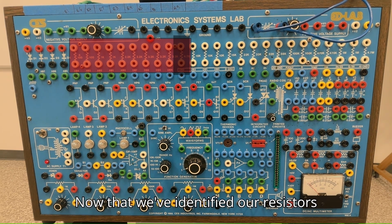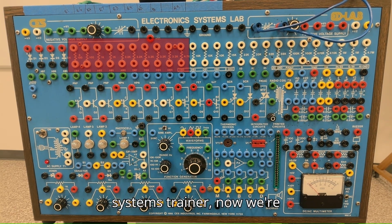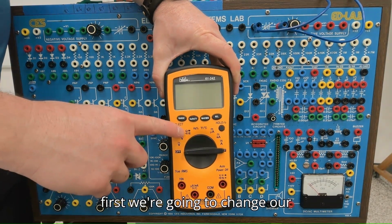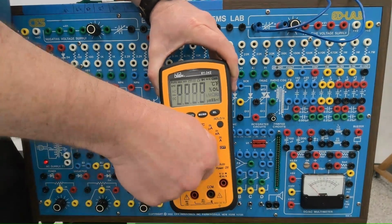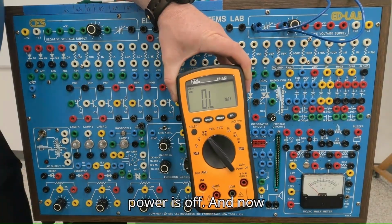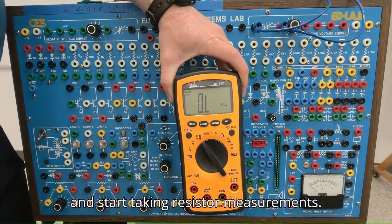Now that we've identified our resistors and their locations on our electrical systems trainer, we're going to verify the resistor measurements again using our multimeter. First we're going to change our meter to the resistor setting. When we're measuring resistance with our multimeter, we need to verify that the power is off. And now we can install our leads and start taking resistor measurements.